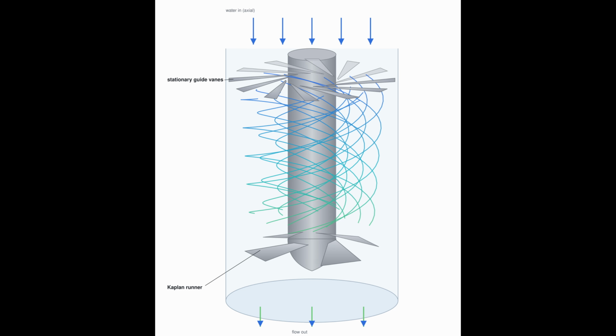Swirl, the secret sauce to low head efficiency. Here's what makes low head Kaplan actually work, and most people have never even heard about this. Swirl. With only 4.8 meters of fall, there is really no energy to waste. So before the water reaches the blade, we deliberately spin it around the machine's axis, the same way the runner turns. That sideways spin is the swirl.